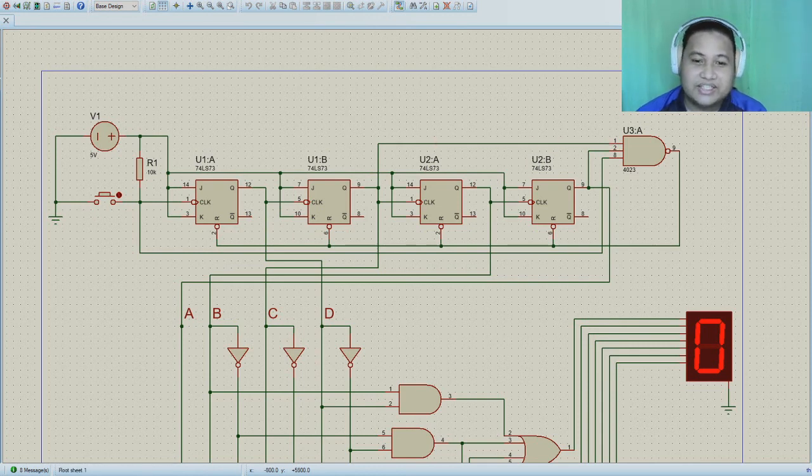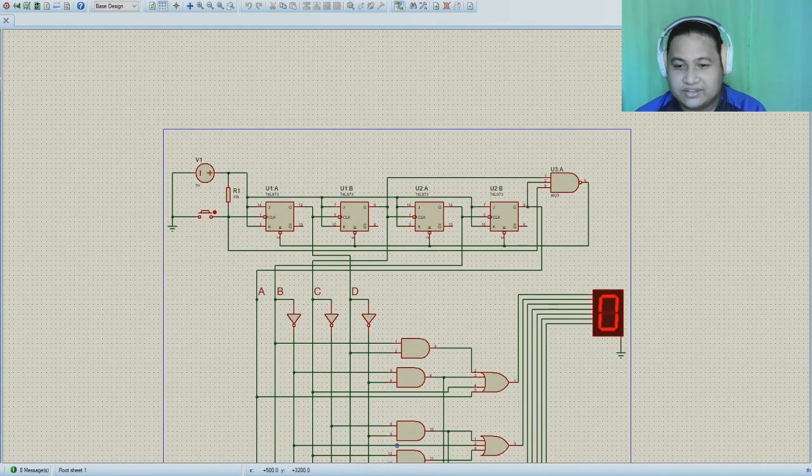Once it reaches the Boolean value of 10, it will toggle this NAND gate to clear all the memory and reset it back to 0. And now our outputs are connected in reverse. So the least significant variable will be your rightmost value in your Boolean value, and so on and so forth.